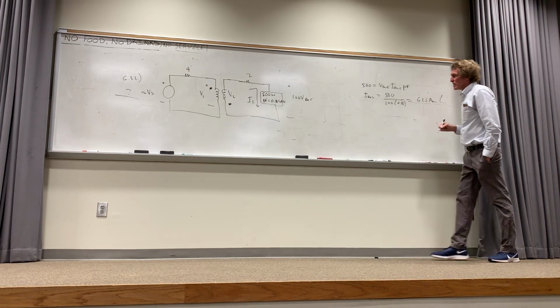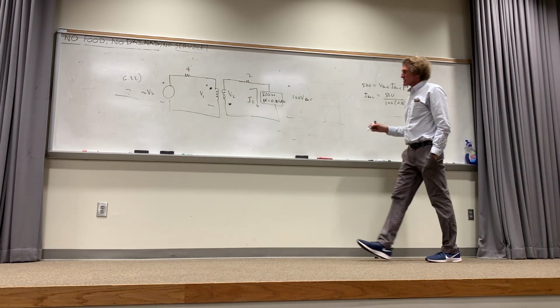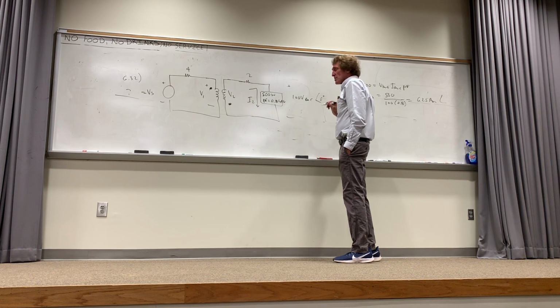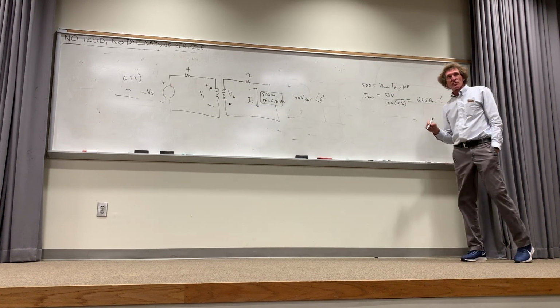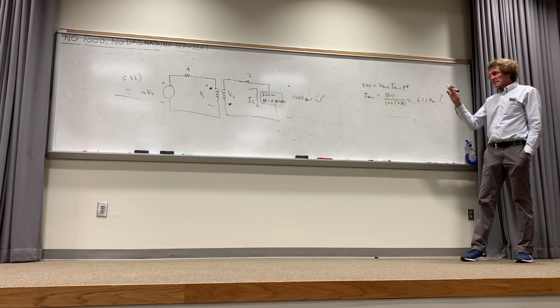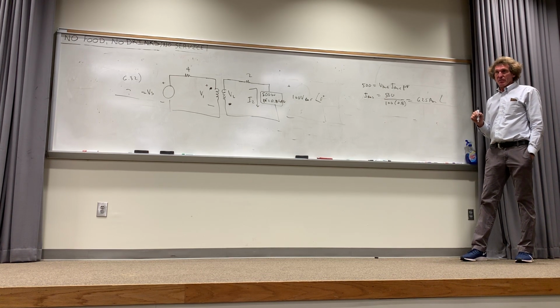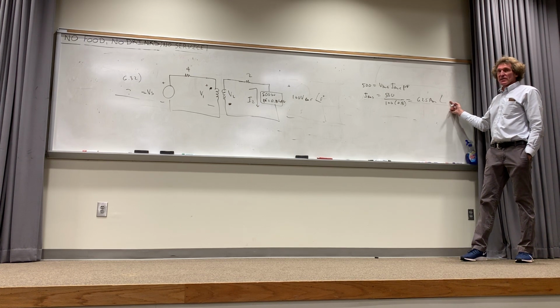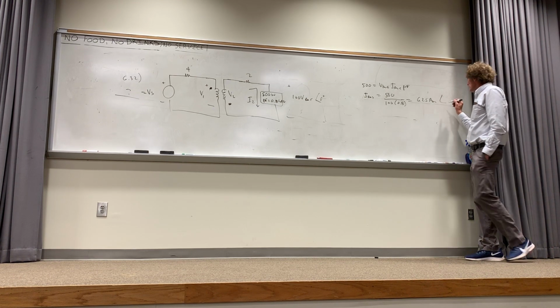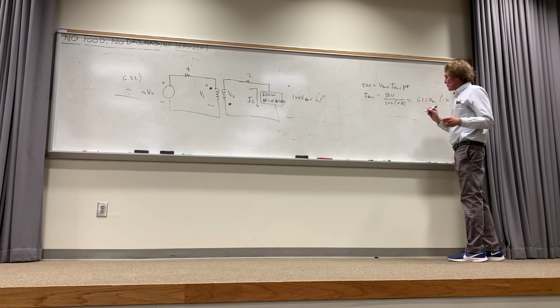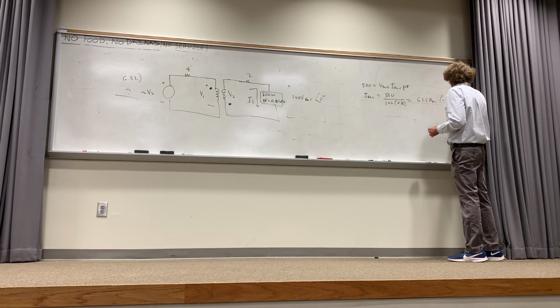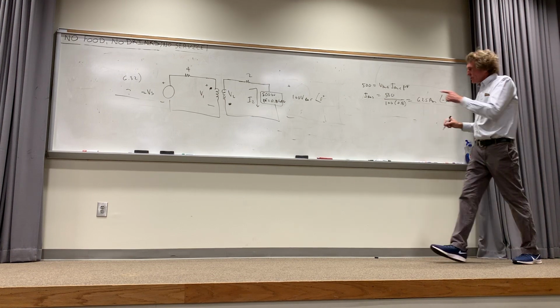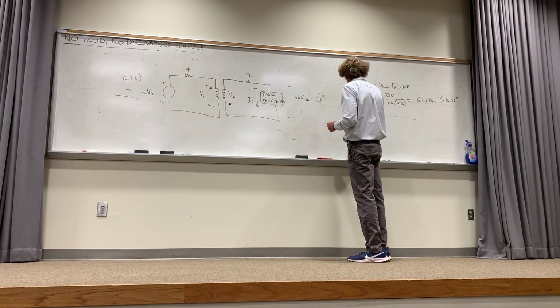And what's the angle? Now, it's not stated, but you can assume this is at 0 degrees, because it's the voltage considered the load voltage. Unless it states an angle there that's different than 0, you have to assume 0. Now, how do I get that angle? Well, I take the inverse cosine of 0.8. It's like 36 degrees, I think, 35 something, right? 36, whatever, and then it's negative because it's lagging, right? So it's going to be minus 36.86 degrees. That's IRMS through there, and that is also I2.